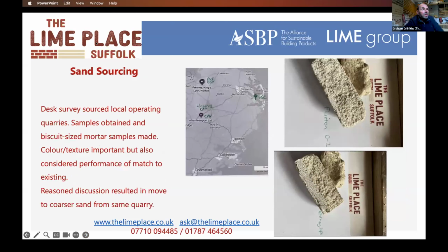I think for me, one of the most interesting things about lime is the difference of opinions. You can see these on forums and Facebook pages all the time, but also the difference in materials. My pallet racking here, I'm sure like lots of other people's, contains stocks of quicklime and putty and NHL binders, but also products designed for very, very specific performance and applications. So generally dry mix products that are bagged, but have been rigorously tested, designed in laboratories, produced in factories. So they are consistent materials with data sheets available. So we know with some of these more modern products what we're going to end up with.